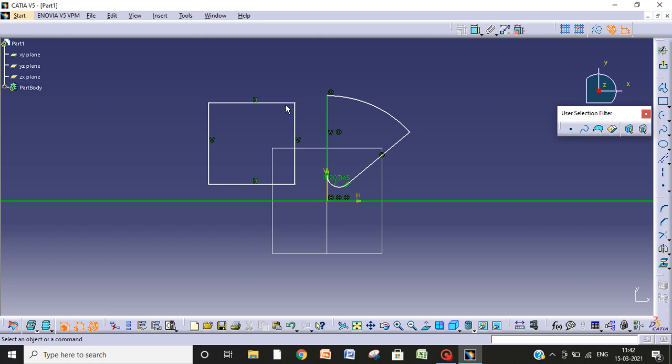I want these sharp edges to be slid like that, like this. This is our chamfer command. Do you know why chamfer and fillet are used? As sharp edges have more stress and can break. So to reduce the stress concentration, we use chamfer and fillet. With a round edge, the force and stress would be divided into this much area and this much. A sharp edge always has a stress concentration.